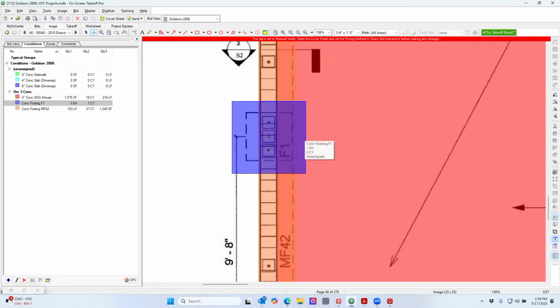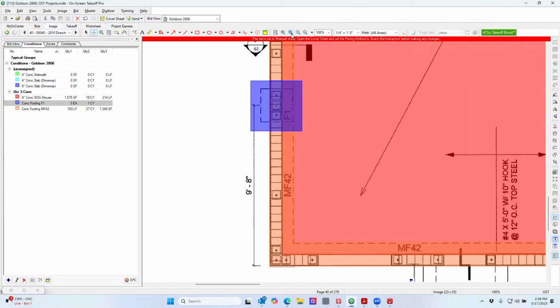So you see how these three cells have this dot in it? That's a symbol for a vertical rebar. And they're probably going to pour all of these cells because they want to mimic a concrete column. They want this to be solid. And I can only assume there's some additional weight that needs to bear at these locations. I can only make that assumption.